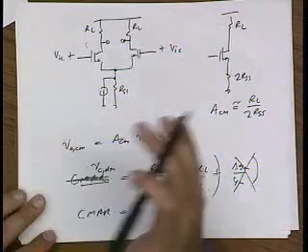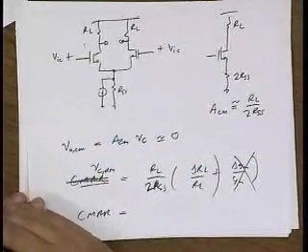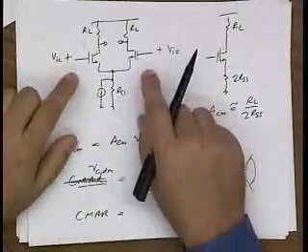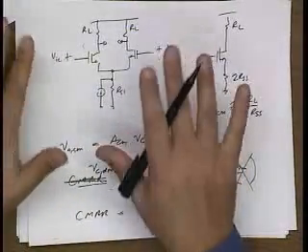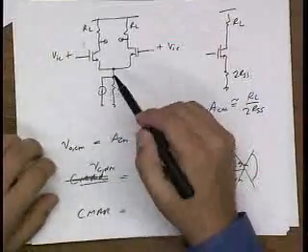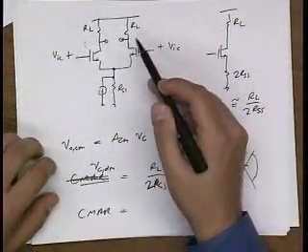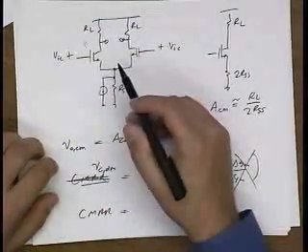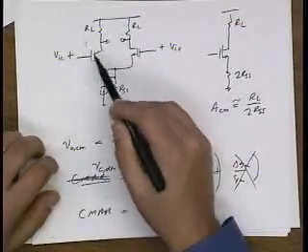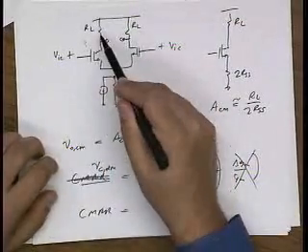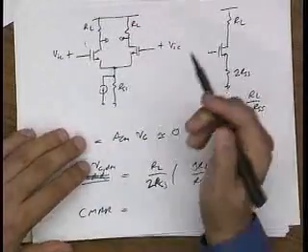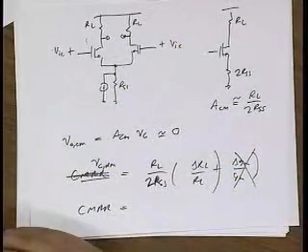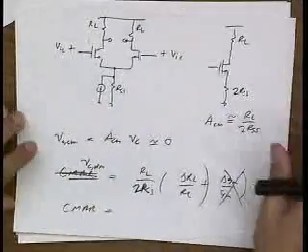Well, actually, most of the time what you say is true. And that's because usually this is going to be in a feedback circuit. And the feedback circuit is going to force the plus and minus terminals to always be roughly at the same potential. And so that means that the impedance here is really equal to the impedance here. But under transient conditions, when the feedback hasn't been able to restore the balance, this transistor may be on hard, this one could be off. All the noise could go here and generate differential noise. So actually, under transient conditions, you will get extra noise. So watch out. Okay.